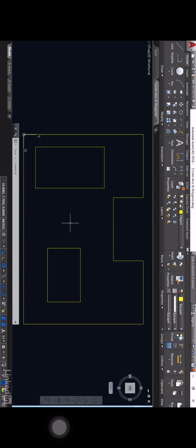Now what I want you to remember is that the bottom left corner of this shape that you've got on the screen is 0, 0 in the model space. Also make sure that you're on the object layer. You can see that in the layers panel there on the home tab on the ribbon. So what we're going to do is look at drawing some circles first of all. Now the first circle I'm going to draw is going to be inside this rectangle here.